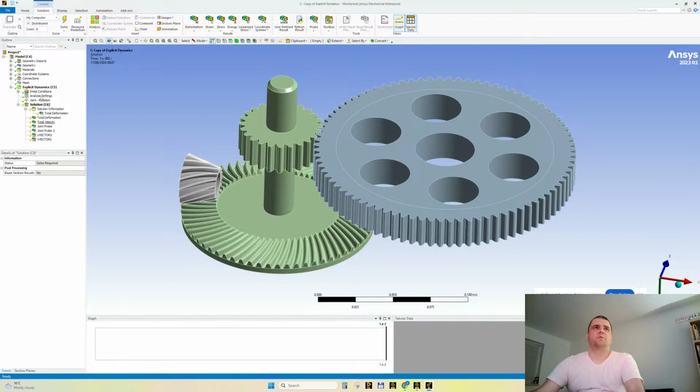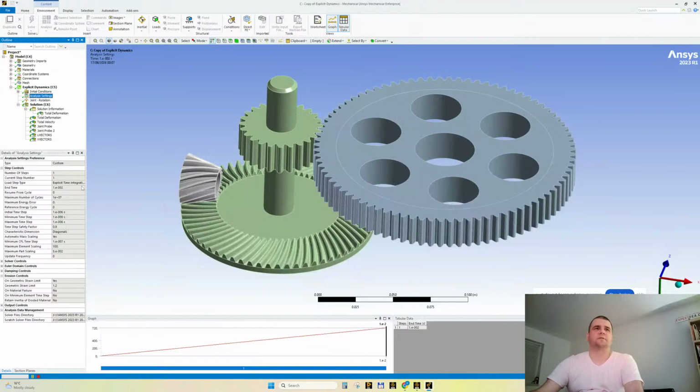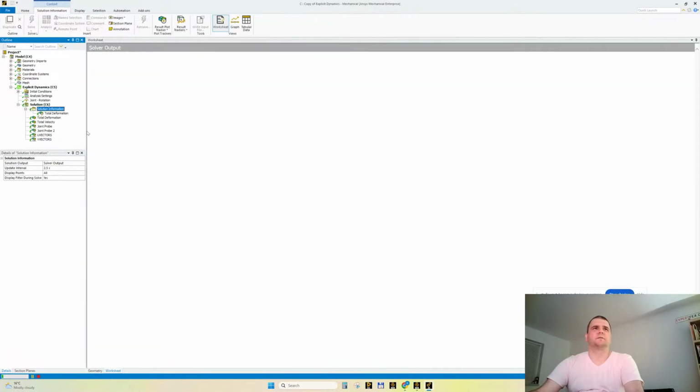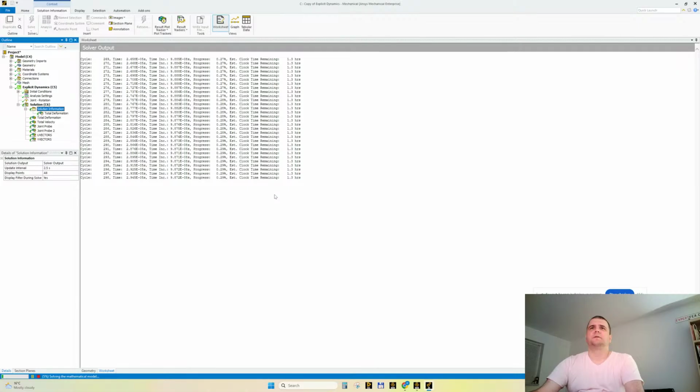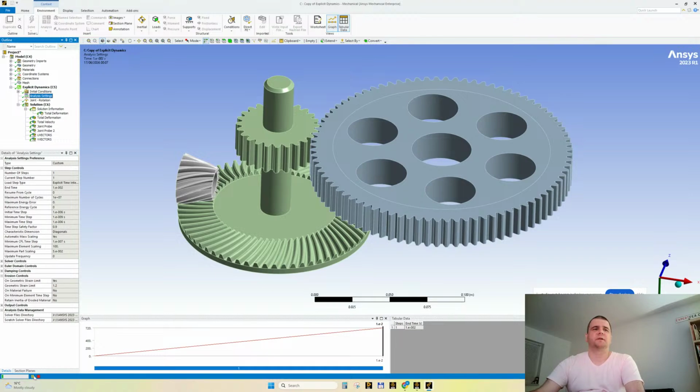So now we have two directions to decrease the solving time. We're going to increase the time step. To increase means going from -7 to -6. And we can also make a coarser mesh in the parts that we're not interested in. 1.3 hours, it's not fun. It's 3 times smaller than what we had before.